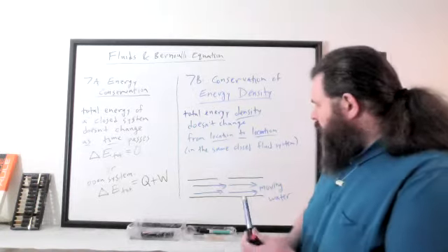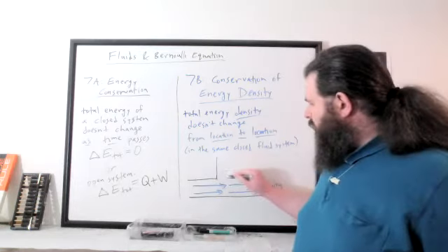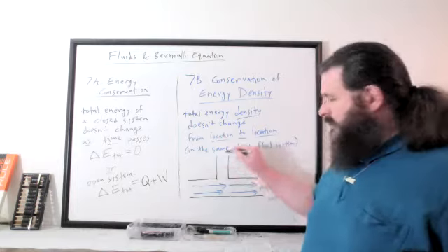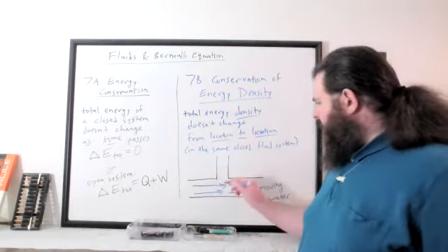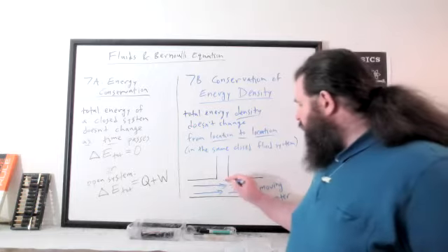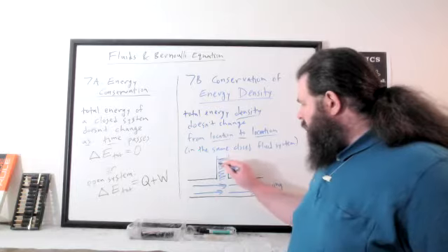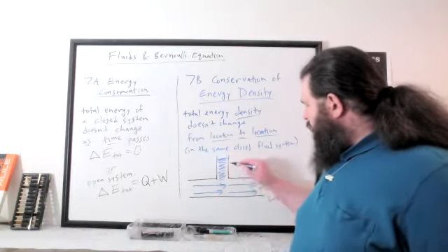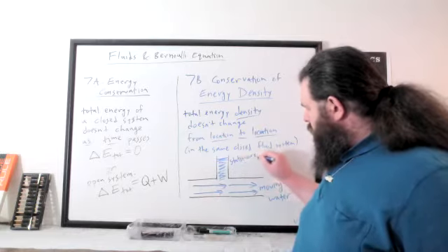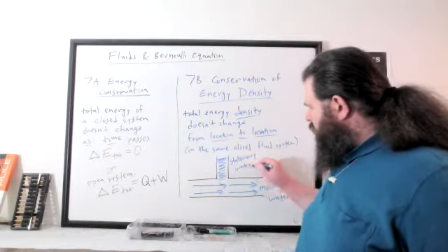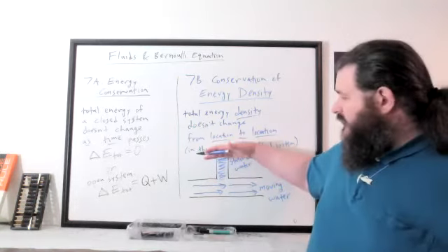And if you've got what's called a standpipe on top of that, basically just a vertical section of pipe sticking out the top, usually with the top end open. And you are in a situation like this, you're going to end up with some of the water supported in the pipe here. And this water here is going to be stationary. It might start to flow up at first, but at some point you're going to reach a level where the water just stays where it is.